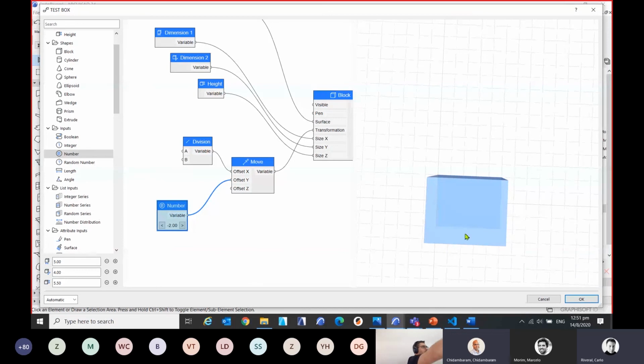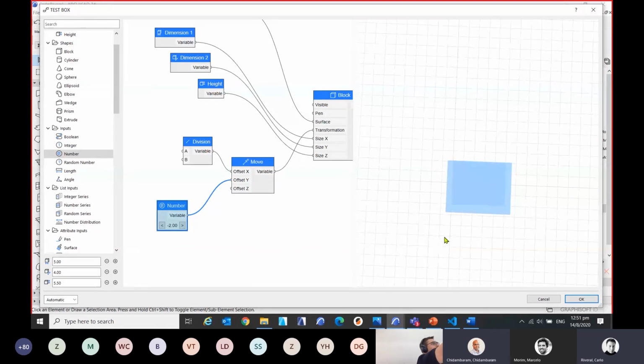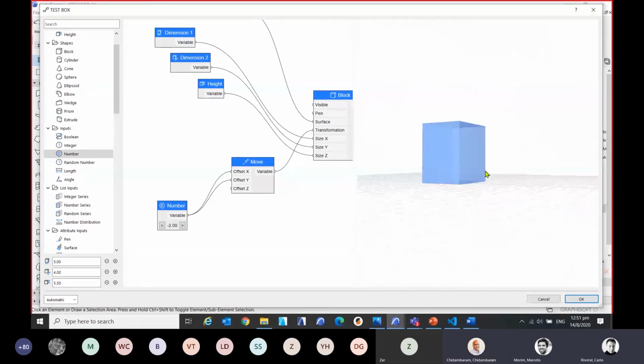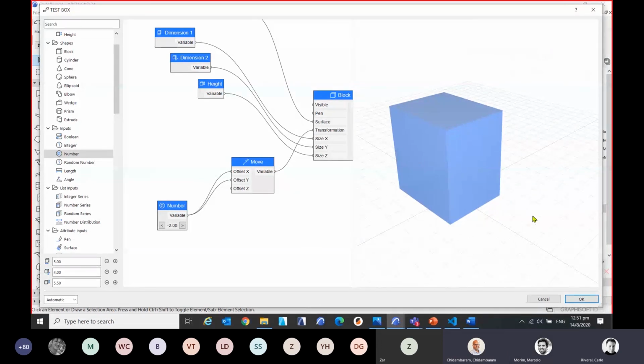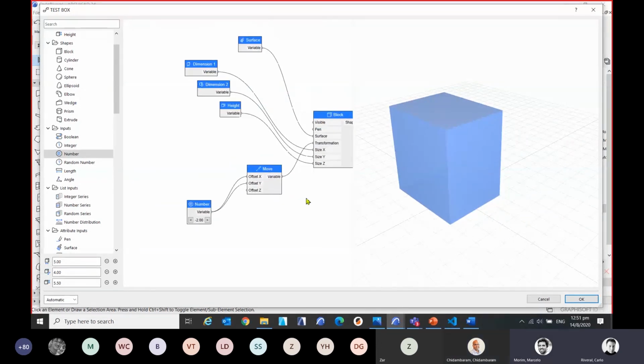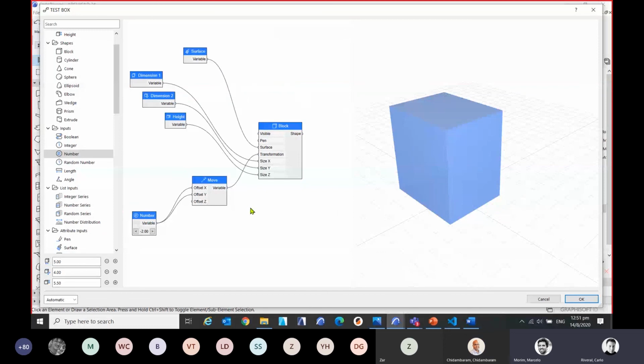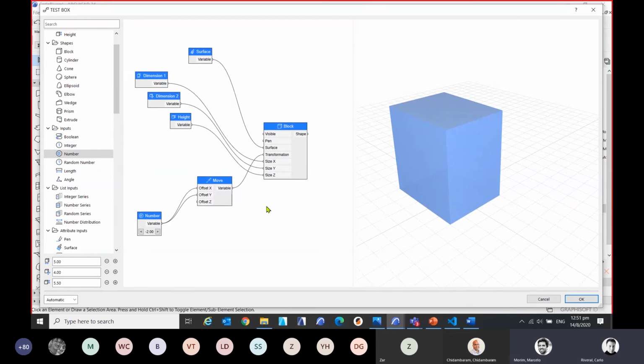So I don't know whether I answer your question. Even the example that I showed before, there were multiple rebars, right? That will become one object. Actually, we can have the parameter there that when we list, it says how many rebars it has. So it can be scheduled with that parameter. But the whole element composed of multiple elements is one object.